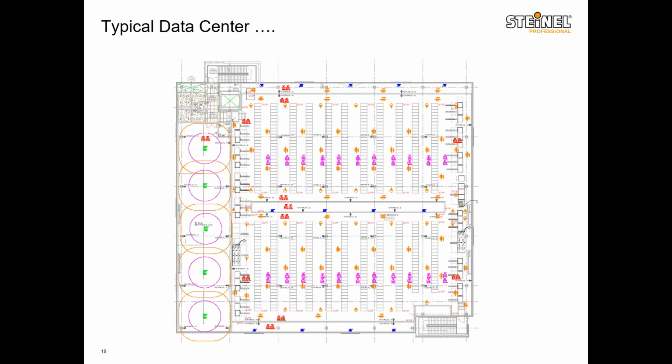And one of the things to note, and I'll show it more closely in a moment, is all of these areas you will control using the sensors like Korea introduced before, but there's always redundant power in the spaces. The redundancy is often even from separate sources, so for separate services. So basically, every other fixture is going to be on a different circuit.